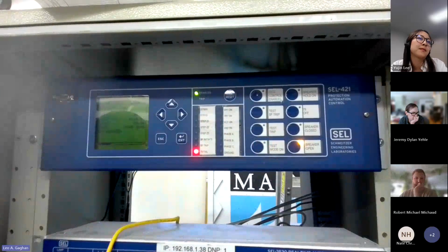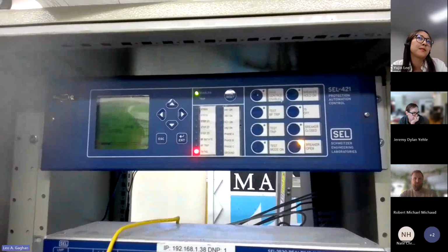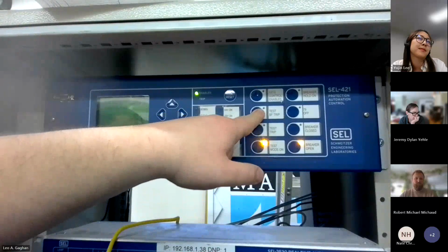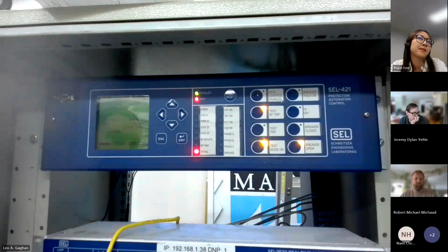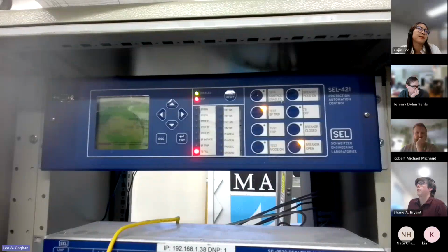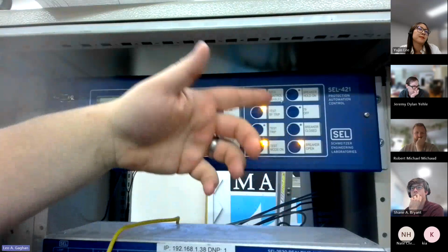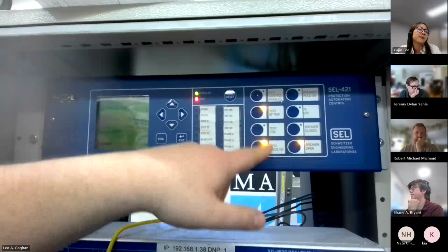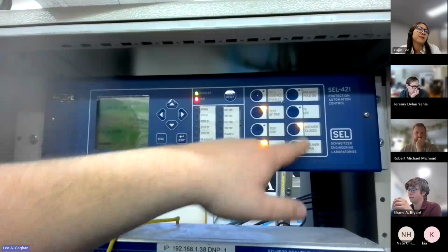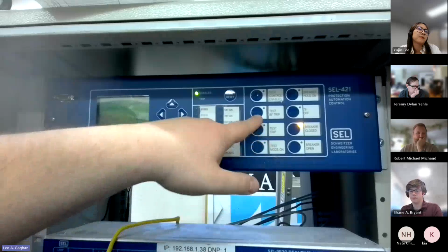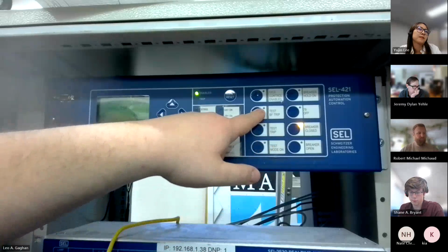That's blinking, we're on. It's this push button 2 that should do it right here. Test BF trip. Let's see what happened. Oh, the breaker was open to start. There's no point, the breaker was already open. Let's close it. Do a target reset. Well, that was done. Okay, let's try it again. Test breaker failure.